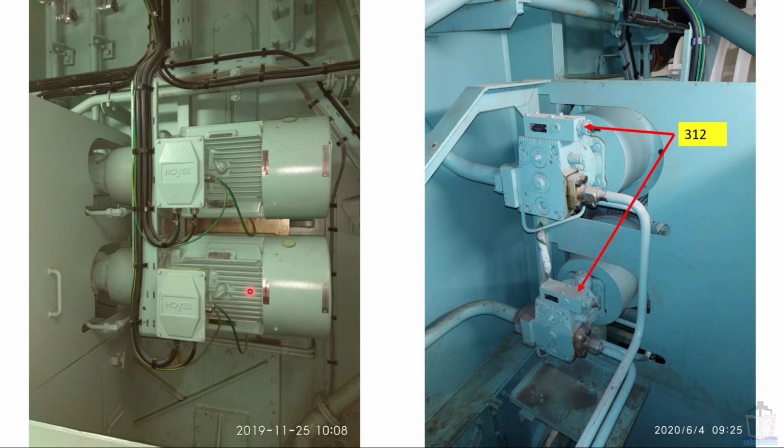These are two electrically driven pumps, basically motors, and these two are pumps. These two are relief valves, valve number 312. This is called the minimess coupling, which is a pressure checkpoint for these individual pumps. In case this pump is malfunctioning or generating less pressure, you can just connect a pressure gauge over here and check whether there is a problem inside the pump or not. If it is not building up sufficient pressure, that means either this relief valve has a problem or the pump has failed. So accordingly you can take action.